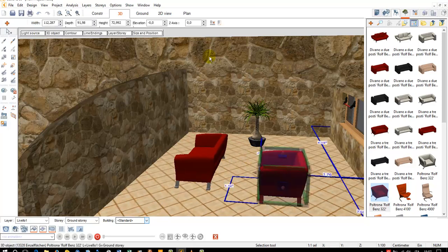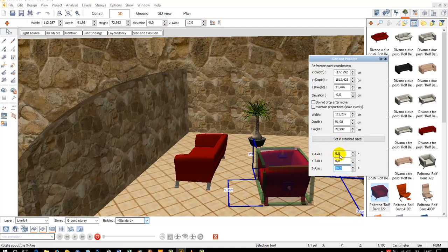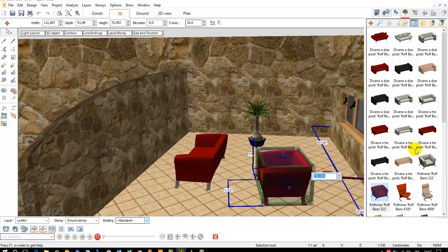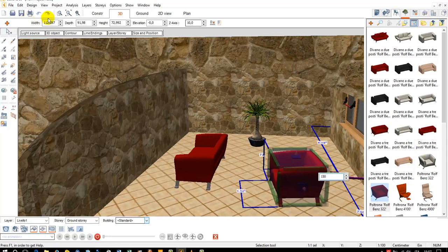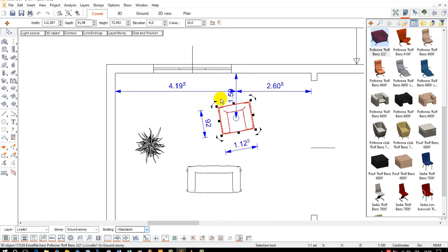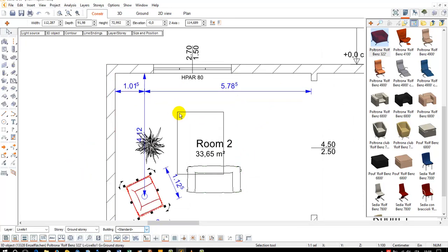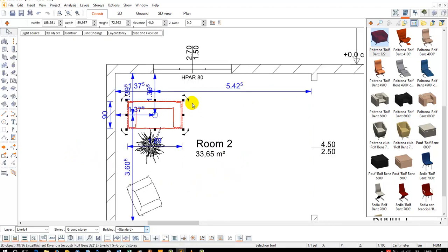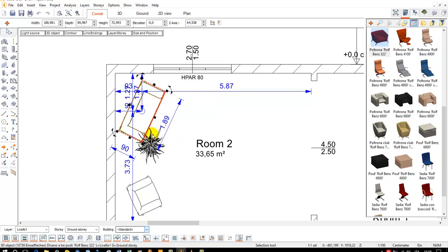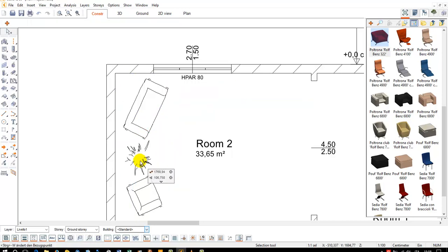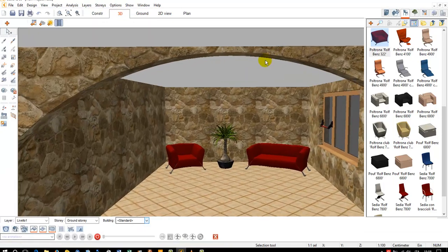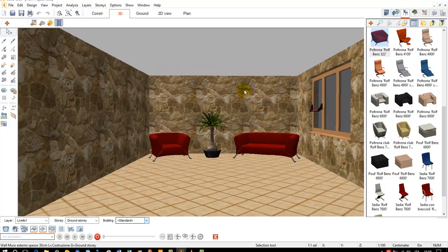Here, if you select an element, you can rotate. Here you can go to size and position. This is all X, Y, Z for the rotation. This is the dimension, and this is the position. But we said we can have also the position with the interactive dimension. I will put here, I will use the mouse in 2D, it's much faster. I will put here, I rotate. It's only so far, we don't need to use perfect angles and so on.